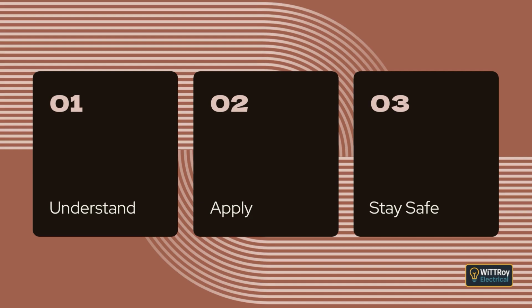Clause 3.15 Busways including rising main systems. This clause explains that busway and rising main systems must comply with AS/NZS 3439.2 and must be installed exactly as the manufacturer instructs. Where a busway passes through a fire-rated part of a building, the installation must also meet the fire penetration requirements in Clause 3.9.9.3 so that the fire barrier remains effective.